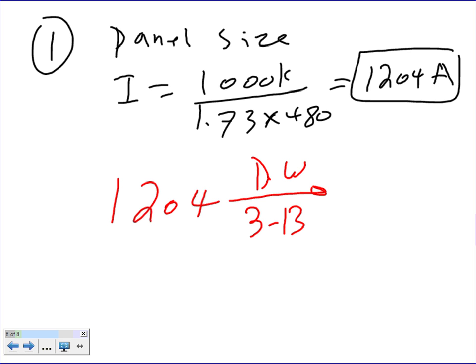If I took continuous load, a future expansion, and everything have been taken care of, guys, honestly, for 4 amps, I would go down. Okay? Did you guys hear me? Everybody got the message? Go down. So I'm going to go down to 1200 amps, just because of this scenario. What's the cutoff that you can go? There's got to be a line that you draw in the sand somewhere. I'm at 1210 now, but I'll just go down to 1200. You know what? For 4 amps out of the 1200 amps, I will go down.